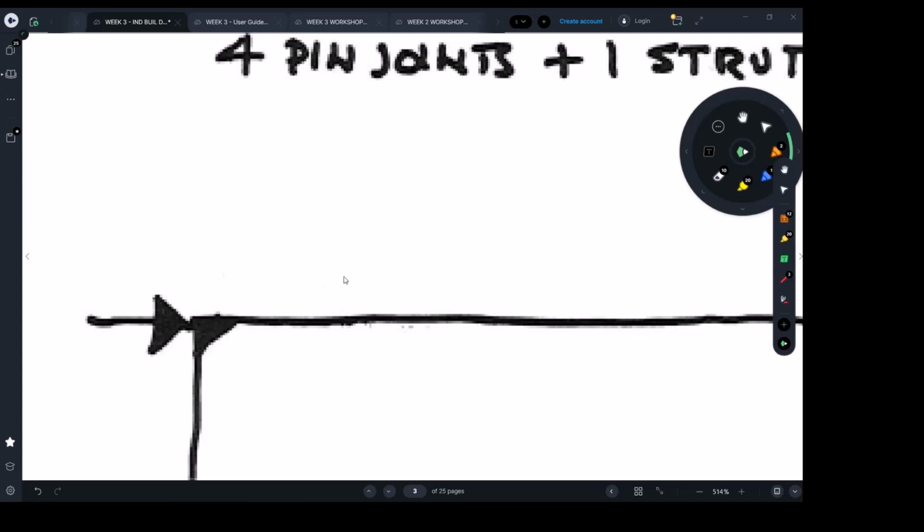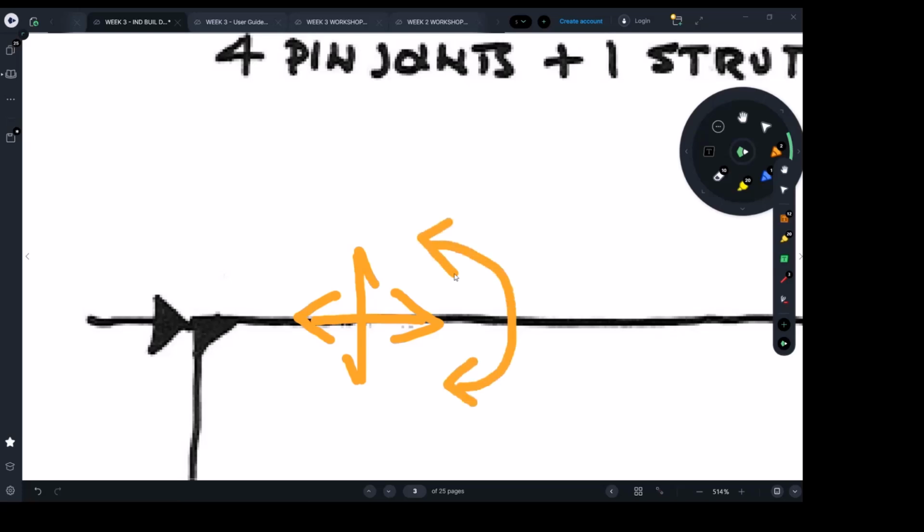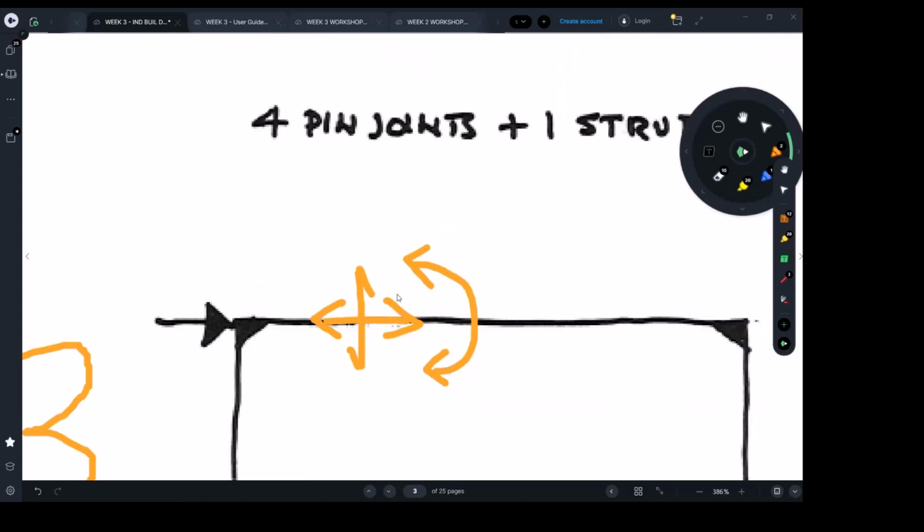What type of actions? We can have axial load, that's one. We can have shear load, which will tend to cut. Axial load is along the rafter. The vertical load, we call it shear load, and it will tend to cut the rafter. And the last one was, what was it? Bending moment. Bending, correct. A bending moment, which can be either clockwise or anti-clockwise, depending on the wind.